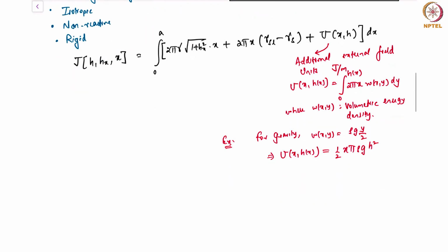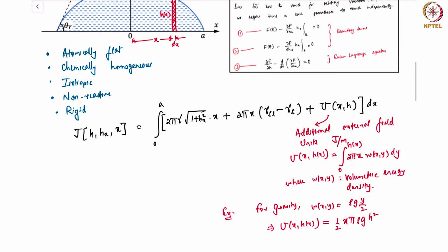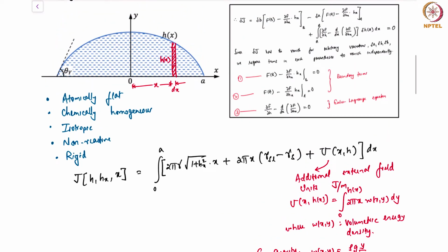So now let's basically do the analysis for this. If you look at the analysis that we had done in the previous couple of lectures, we basically wrote down the energy functional. We looked at the variation of this energy functional, which I called delta of J. And then we set each term in this bracket, in this variation, to 0. And when we did this, we got these boundary terms, which I'm highlighting for your benefit.